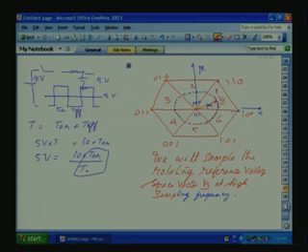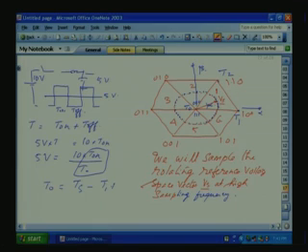Let us take 1 0 0 in a sampling period, 1 0 0 is applied for a period T1, and 1 1 0 for T2, and the 0 vector for T0. So the T0 period is equal to the sampling period Ts minus T1 plus T2. First of the period will be 0. Now you have to find out T1 and T2 such that the volt second along alpha beta is matching. So how do we find this?